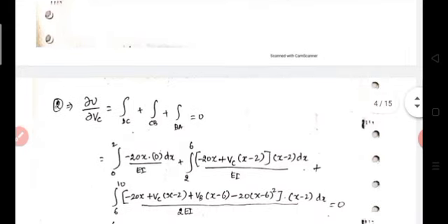Then substitute in equation 2. From equation 2, we know that dou U by dou Vc is equal to the integration of Mx dou Mx divided by dou Vc into dx divided by EI equal to 0. This is the general equation. The beam is a 2-span continuous beam with 3 segments, therefore the integration of the DC portion plus BC, then BA, is equal to 0.